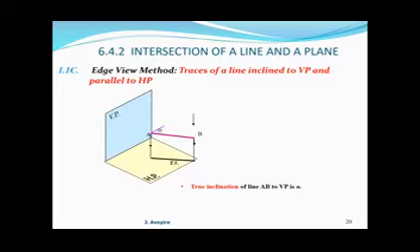Here we have the top view, and that's TV, AB. That is the angle of inclination to the vertical plane. Note that the angle is also measured with respect to XY, which represents the edge view of VP. Now, if we project for the front view, we obtain a horizontal line, AB. That's the front view. So we now look at the correlation between these two.